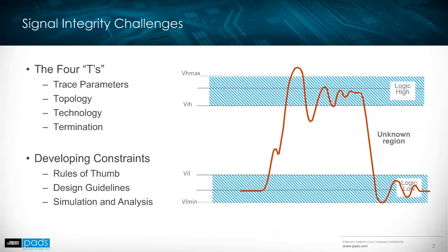These are decisions that engineering teams are already making today. To minimize issues such as crosstalk and noise, and to achieve correct timing for their design, engineering teams typically use their experience and rules of thumb to create constraints needed for their design. These constraints will need to go into the constraint management system and drive the PCB routing process. Engineers may also need to read design guidelines to see how to approach the design given the technology or application. Another method is to simulate. Simulation helps to ensure that the technology or application being used on a design will work right the first time.